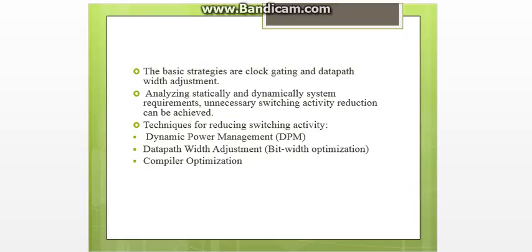Next is the compiler optimization. It uses an instruction scheduling technique to reduce power consumption due to off-chip driving. This technique reduces transitions on a data bus between an on-chip cache and a main memory, and as a result, power consumed by off-chip drives in the main memory is reduced.